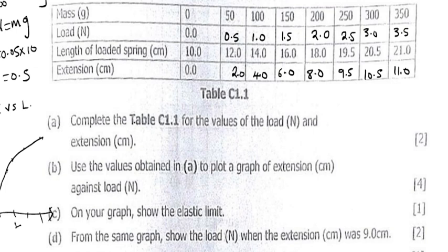In my diagram, where it was turning from will become the elastic limit. So on your graph, you're supposed to check the point where it no longer became a straight line, where it started bending. That is the point where the elastic limit is.